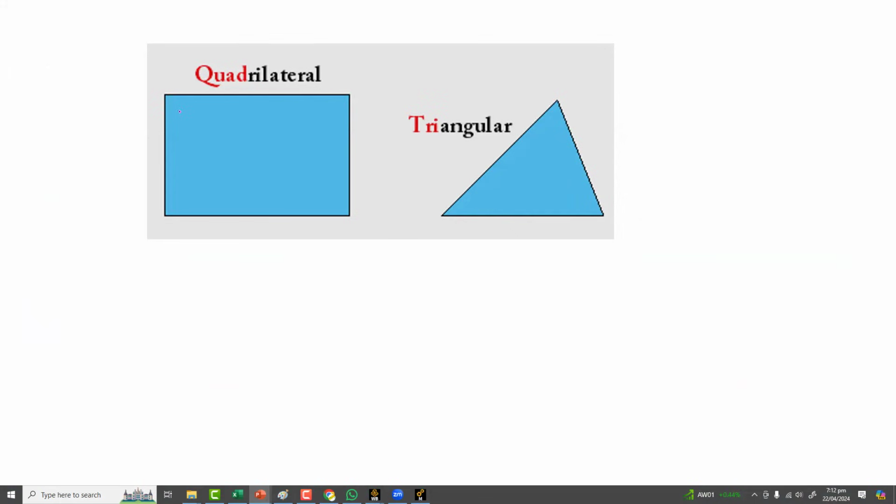Okay, a rectangle will have all angles at 90 degrees. Okay, and if you see any distortion there, then this is no more a rectangle. So this may be a general type of quadrilateral. This can have a shape maybe like this. Okay. So at this point, when all the angles have 90 degrees, we have three quality metrics. One is the orthogonal quality. This orthogonal quality is, I would say, a very comprehensive type of quality metric.